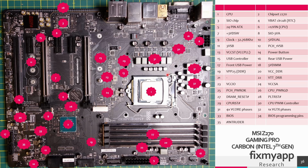The SVID protocol uses three signals. First one is the clock signal, then we have the data signals, and there is an alert signal. So the clock signal provides the timing signal for communication between the CPU and the PWM controller. Then we have the data signals, which transfer voltage requests, power state commands and fault reports. And the third signal line is called alert active low. So the alert signal indicates that the PWM controller has information to report back to the CPU, such as a status update or a fault condition.